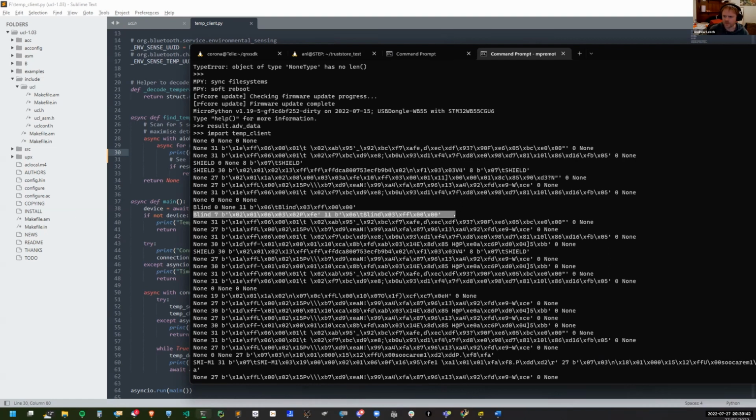So here's one where the advertising packet is 7 bytes long and the response packet is 11. And in the response packet is where the name is hidden and things like that. Similarly up here, in Shield, there's a 30 in advertising and then another 8 in response, which again, the name's hiding there. So it sort of depends on how the device has been designed, where they put the important data. But hopefully, see how that goes.